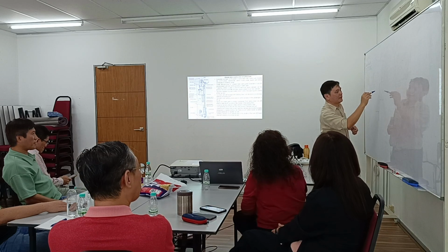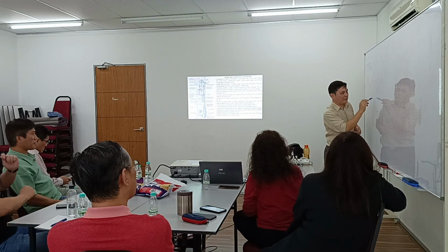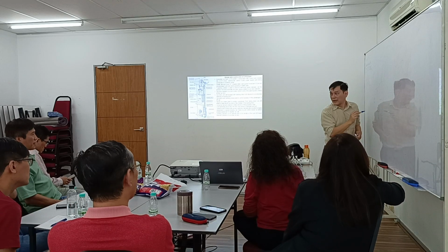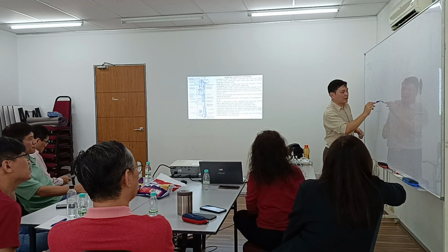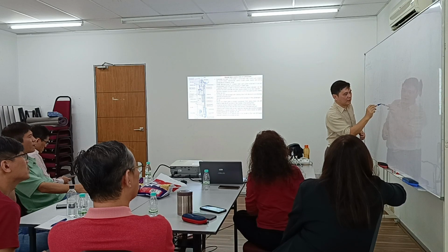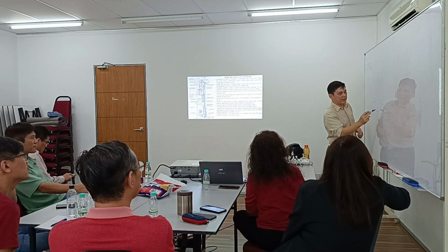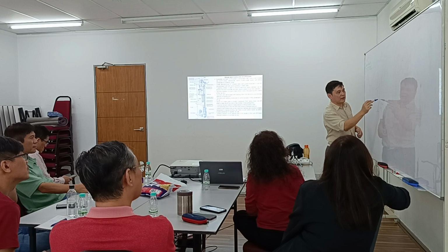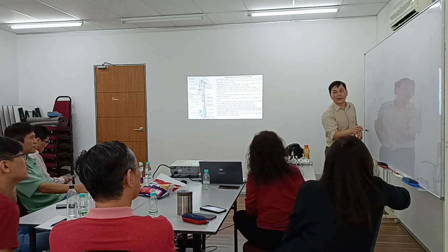This is a lift car, and usually the opening is 2 meters or 2.1 meters. 2.1 meters, okay. The apron design is actually around 700 to 750 millimeters. The reason you want to cover that is in the event the lift gets stuck somewhere here, there is coverage so that people will not fall down.